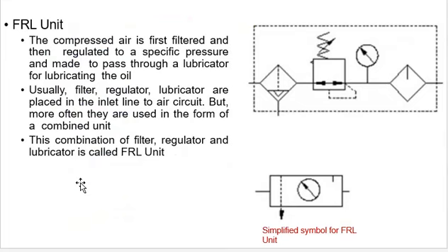Then next, if we combine all these three components, we get the FRL unit. What is meant by FRL unit? F means filter, R means regulator, L means lubricator. So filter it, regulate it and lubricate it. If we combine all these components, we'll get this particular component.